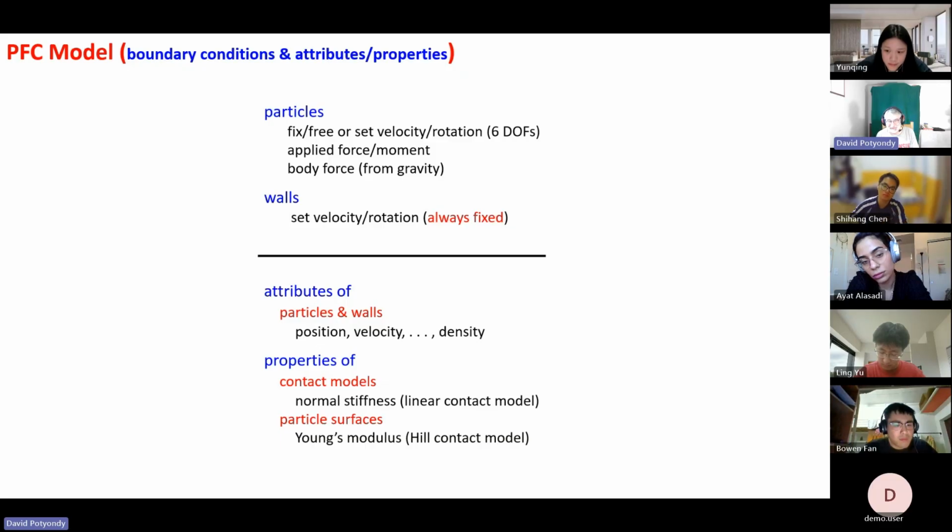I'm not saying the displacement is 0. There is no concept of displacement in a discrete element model. Displacement is a concept of a small strain system. We have a reference configuration and we look at motion relative to that reference. That's what we think about as a displacement. In PFC, you're not doing that. You don't have a reference configuration. All that you have is, at the current time, at the current state of the system, you have velocities everywhere. That's all you have.